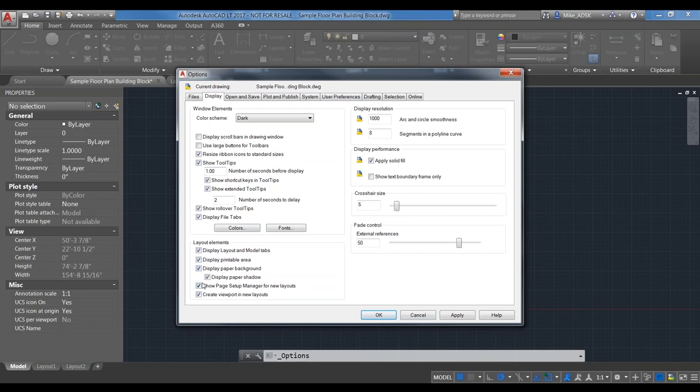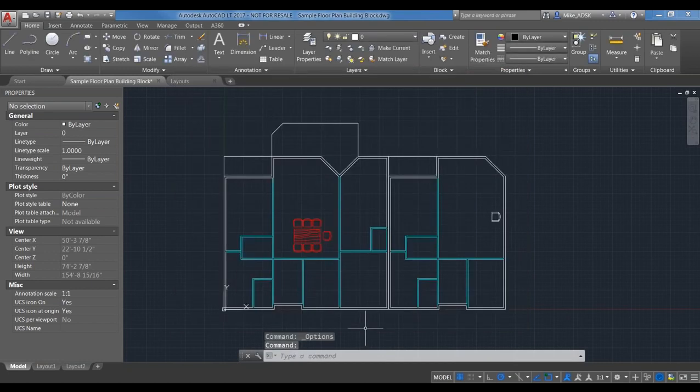Awesome. Thanks, Zach. Alrighty. So, differences between model space and paper space. Down here I have two paper space layouts, and then you have the model space one. As I had mentioned before, in model space you can really only have one scale. You can think of this one as real world units. Then when you have your paper space, you can include more than one scale. There is a limit to it.